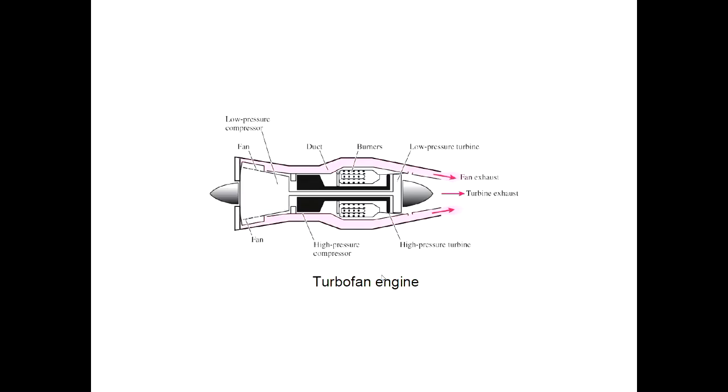Okay, again, this is a more detailed structure of the turbofan. Actually, this is a better illustration. You have a fan there to bring the air in continuously, and you have the compressor, which is here. Part of the air goes in the duct in this purple area, not going through the engine. The rest of the air goes through the compressor, then combustor, then through the nozzle. And they join at the exit of the nozzle.